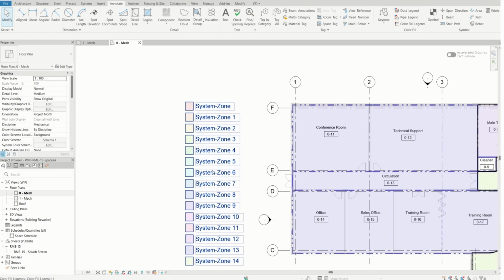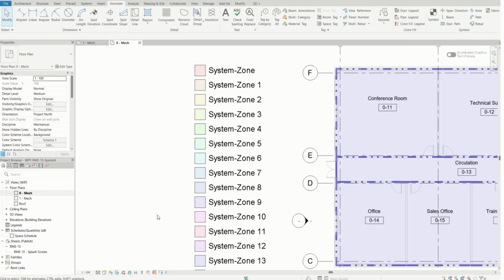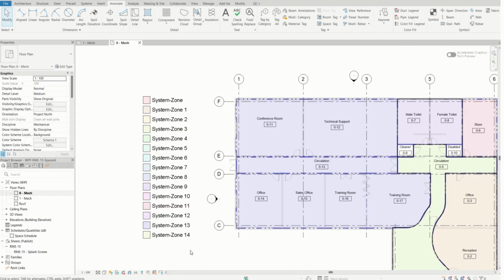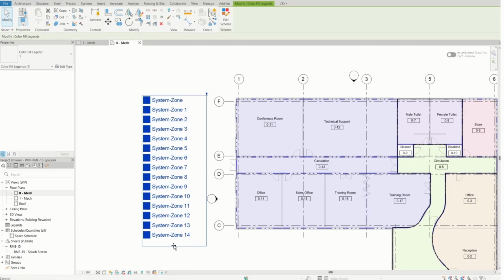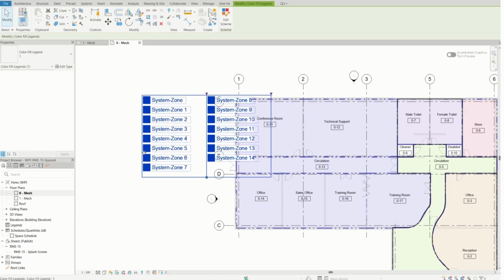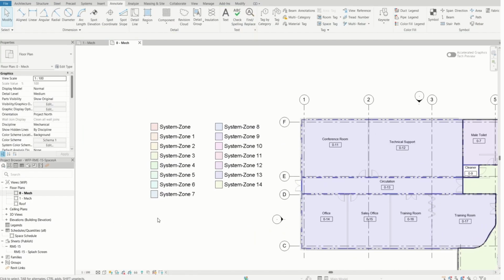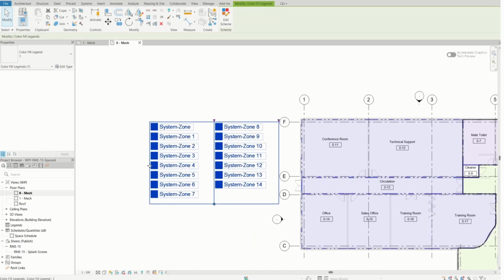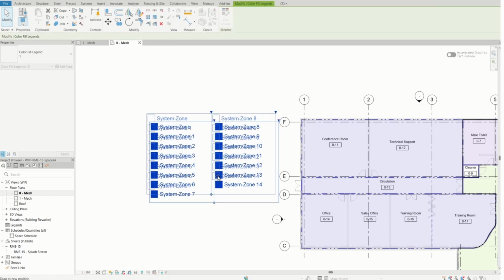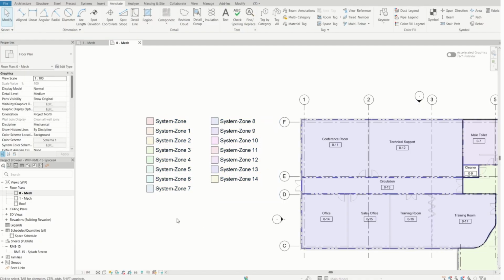And that concludes Module 15, Spaces, Zones, Areas and Volumes. You've now seen how Revit defines enclosed regions, how spaces store mechanical and electrical data, and how zones bring those spaces together for environmental analysis. You've also learned how to calculate areas and volumes, how to schedule and tag spaces, and how to use color schemes to communicate design intent. These tools are essential for early-stage design, energy modeling, and coordinated MEP workflows.